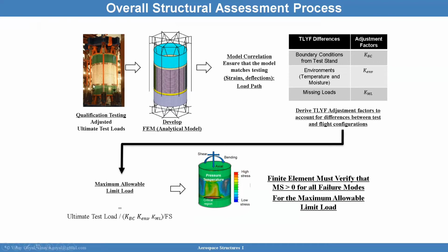So, you may want to try to figure out what are the right loads I need for the design. And so here you have the qualification testing. This qualification test needs to be modeled, and you want to model this before you actually test to make sure you can come up with the right loads that you need in this test. Now, you could test hundreds of combinations, but that might be inefficient. The right thing to do is to figure out, hey, what are the load cases I can apply that could envelope other load cases? And the idea then is to come up with an understanding of the loading environments that I need for this testing.